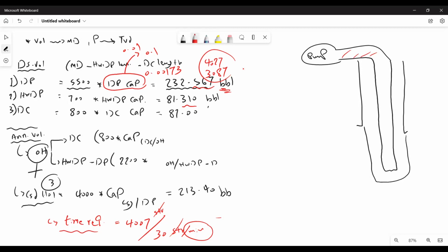Once pumping reaches kill rate, 30 SPM for example, we have here on the drill pipe gauge the ICP value, let's say equal 900. Once we are pumping the kill mud weight inside the well, the drill pipe pressure starts to decrease till reaching FCP once reaching the bit. Let's say it equals 400. So the pressure dropped from 900 to 400.